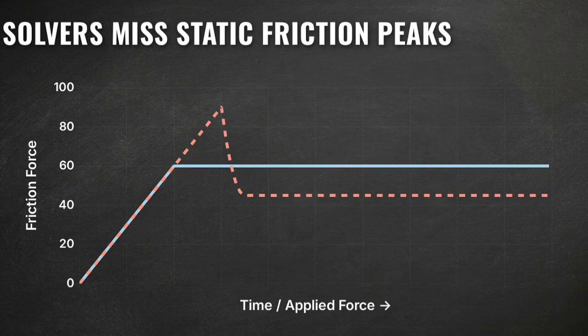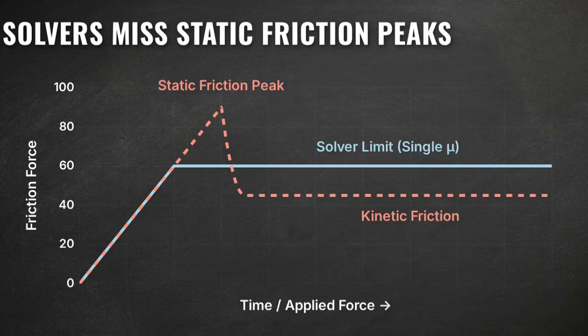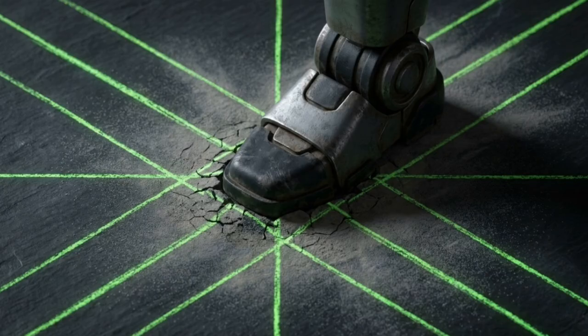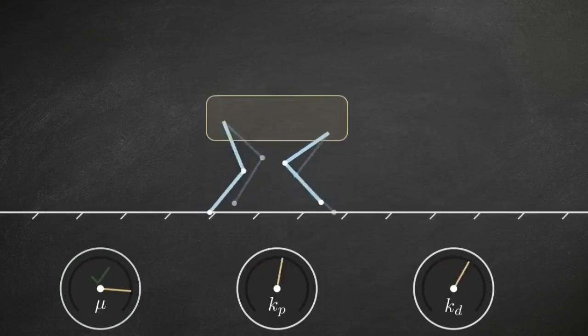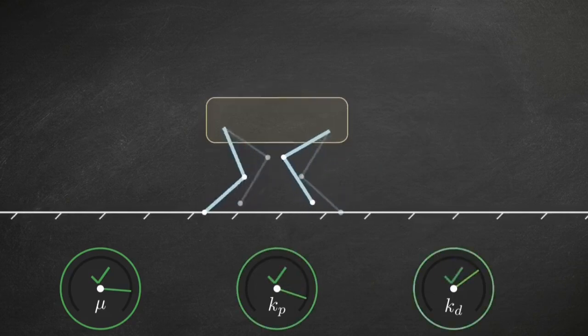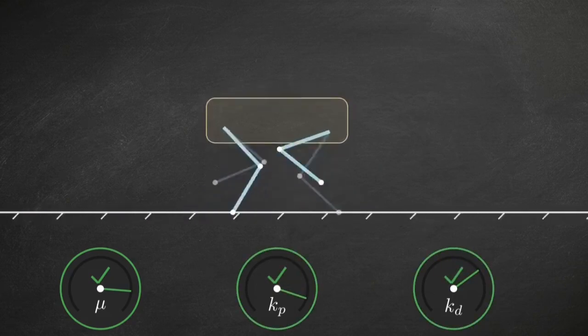So, the fidelity of the locomotion simulation is tied to these ground contact parameters. Precisely calibrating the interaction between Kp, Kd, and mu allows a theoretical gait to behave predictably when it meets the digital floor.